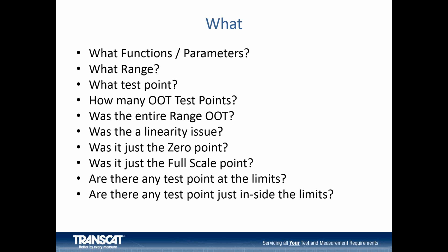All right, so what? The first thing you need to do is to read through your calibration data to get a firm understanding of what specifically failed calibration. You need to identify what functions, parameters, ranges, test points. How many test points? Was it a linearity issue? Are there zeros out of tolerance? What are the test points at the limits? Are there some right inside the limits? This is all the information that can help you lead to better conclusions.